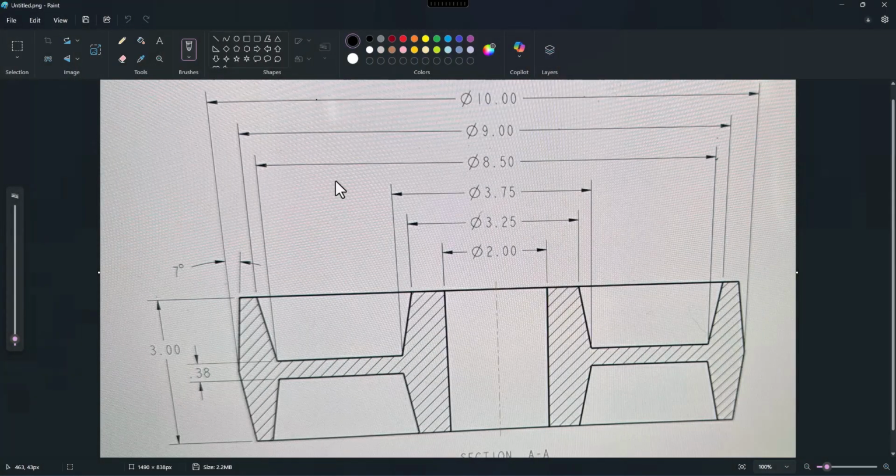Hi folks, in today's video tutorial I'm going to show you how to model a complicated Revolve feature with a complicated shape. We will split this shape in half, so we will create half of the shape and then mirror the full feature, because it would be much more complicated to do it in the sketch for Revolve. So let's have a look, yeah?